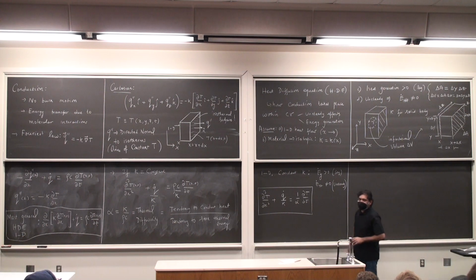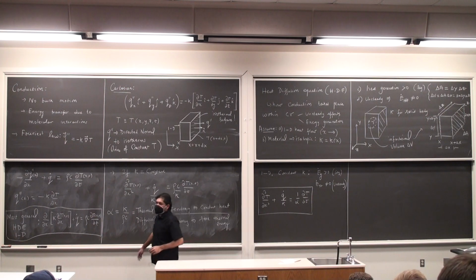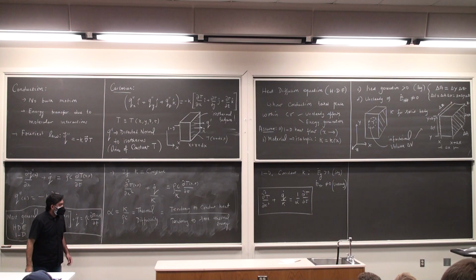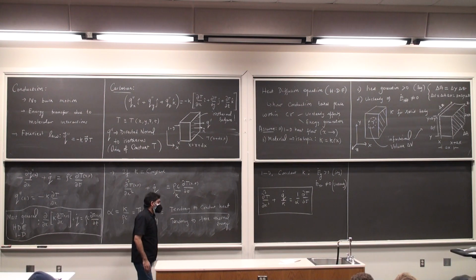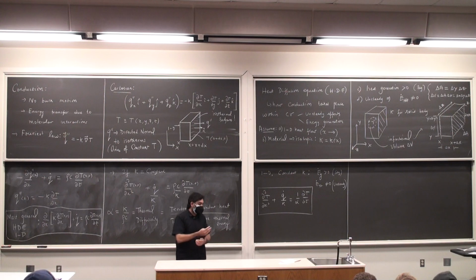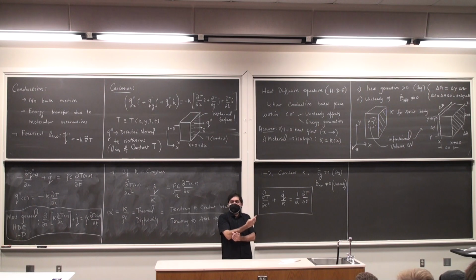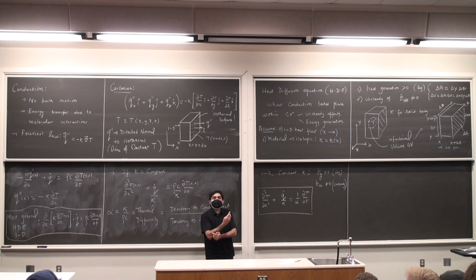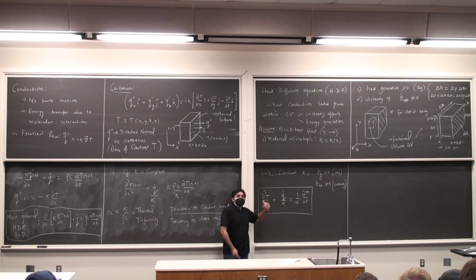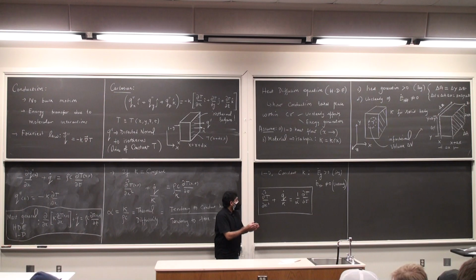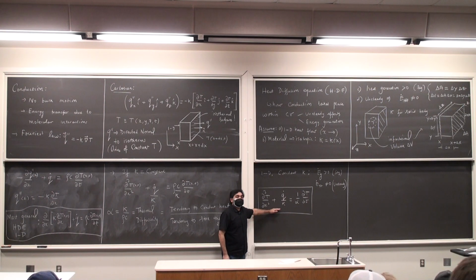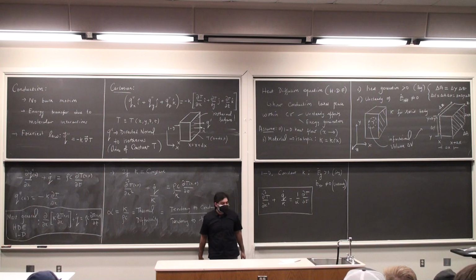Why are we doing these things? What's the purpose of these equations? One purpose could be the following. Suppose I experimentally determine, using thermocouple measurements and so on, here is the temperature profile through this medium. Then using that temperature profile, I can calculate any kind of a quantity. For example, if I need heat generation, I can calculate that. Or if I have certain conditions that are met, I can find out how the temperature is evolving as a function of time. This is a partial differential equation. Its solution is non-trivial. You will have to use numerical methods. Okay, so that's one thing that we can do.